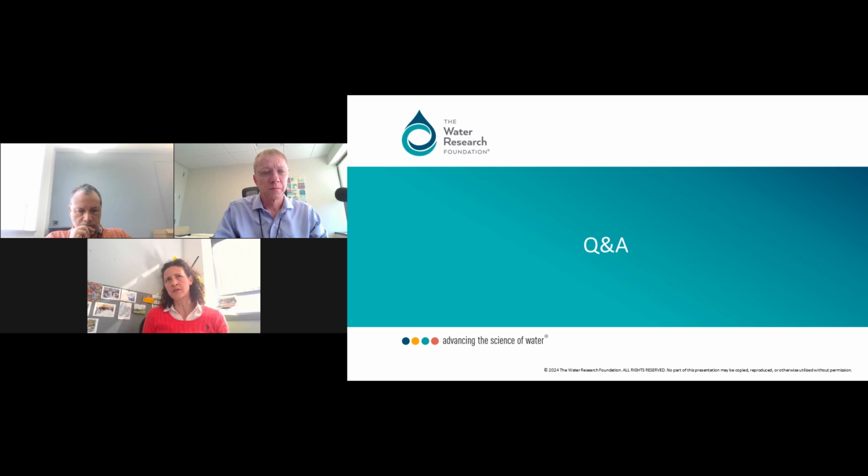You saw the improvements. And the HRT of that facility is quite low. It operates on the aerobic side between 3.5 and 5.5, depending on the diurnal peaks coming in, hydraulic peaks coming in. So that's on the lower end of HRT for aerobic conditions. And the SRT at that facility, we kept steady at 6 days. So that's not as low as we probably could get, but yeah, that's a long-winded answer. I covered a couple of the questions, Chip.